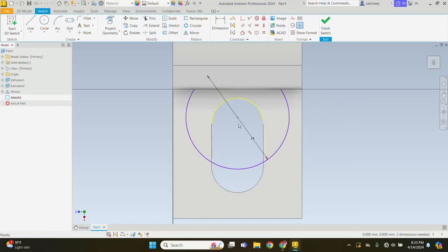This is why we needed to project that geometry. So we'll put a dimension in between these 2 points, which is going to be 1.5. Enter. Okay, so we'll apply the final dimension, which will be between the center of the circle and this line. We'll go with the 15 we have, and then okay.